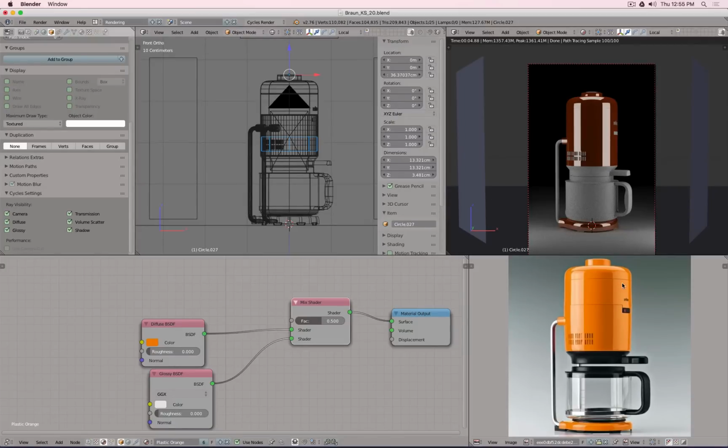But we know that reflections with plastic are not the same on a geometry that is perpendicular to the camera, contrasted to geometry that is tangent to the camera. We know that everything that's perpendicular has less reflection, and when it goes to tangent surfaces, the reflection gets stronger and also more saturating. But it doesn't really saturate or overlay and hide the diffuse.